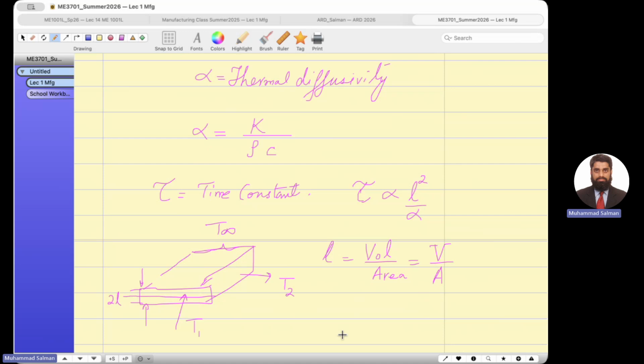So then you have to apply the first law of thermodynamics, which equates to the convection. Over here, this is the surface temperature radiating to the environment, but inside is conduction. Inside is conduction, at the surface it is convection. So you have to equate both convection and conduction, because heat has to be released to the environment in the end.